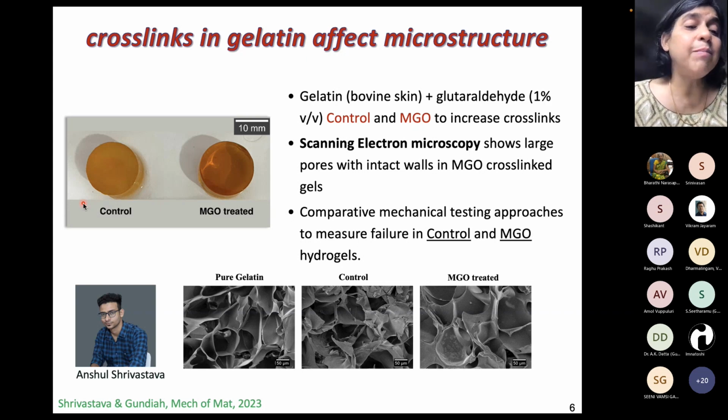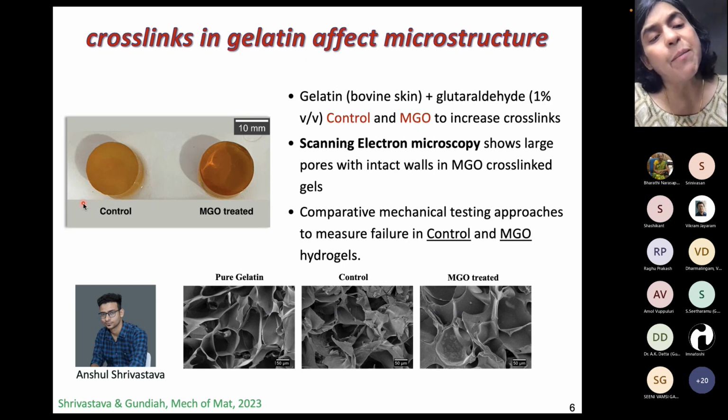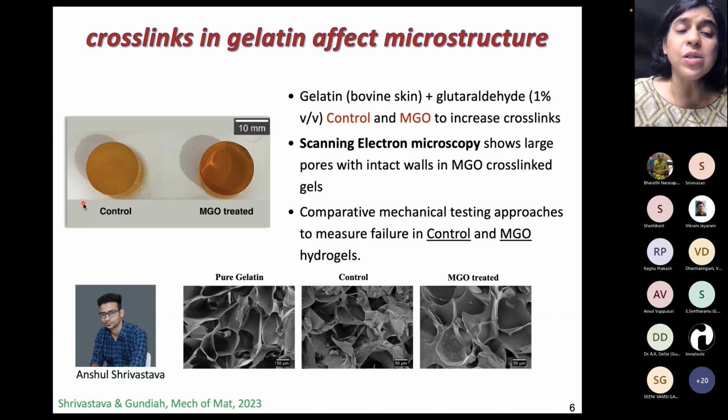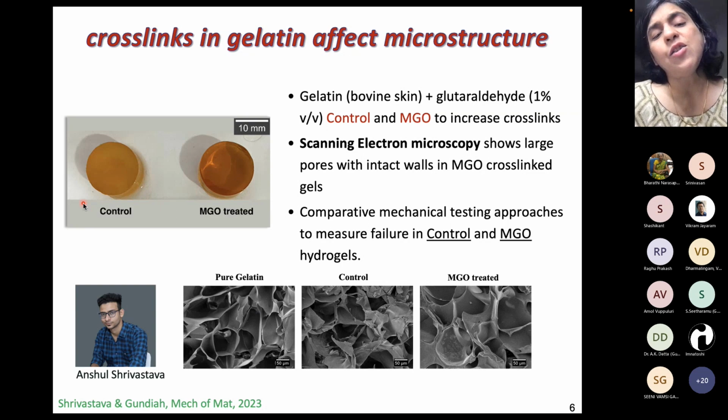One idea which has been in vogue for about 15 years now is the use of double network hydrogels, where one network acts as a sacrificial layer and the other allows these very large deformations to happen. However, in the case of our MgO hydrogels, we have only introduced additional chemical crosslinks. So what we anticipate is a much higher modulus.